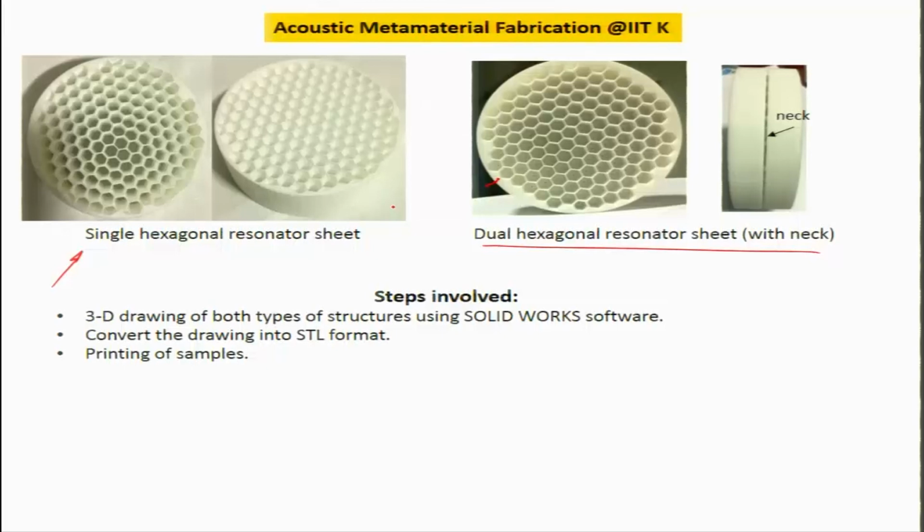way of manufacturing. But the idea here with the CAD to reality concept, as is being promoted by this FDM process, this fused deposition process, makes it very simple to manufacture such geometries. You can see here small channels interconnecting two different layers, layer 1, L1 and L2, each of which has these honeycomb-like structures. Such a three-dimensional complex shape getting printed through normal machining is next to impossible, and it can happen only while you are building things additively.